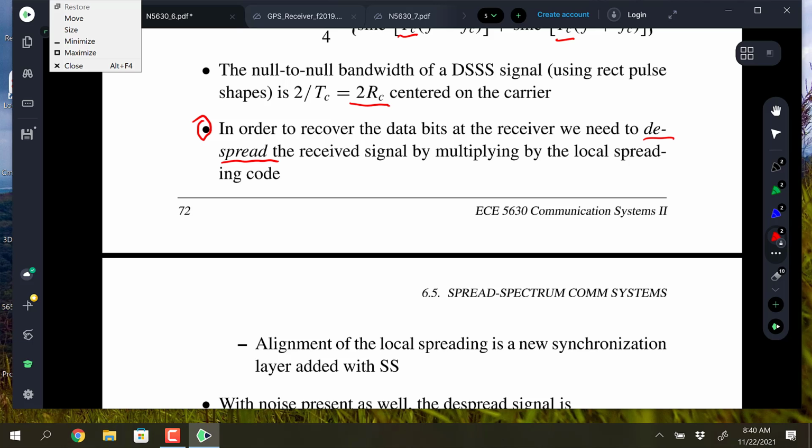Yeah, start from there. But then there are the Gold codes, which are used too and are part of that. So there are two layers of coding, but the long code in second generation CDMA is the one that carries the processing gain of the spread spectrum. We're going to talk about multiple access after we go through some more properties, but there are two primary applications of spread spectrum. One is multiple access, but the first one is the anti-jam capability.